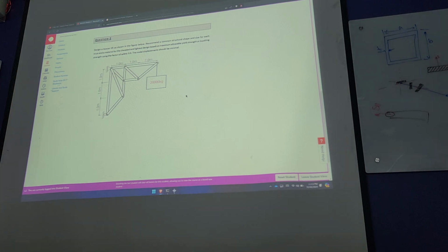One important thing, it's worth remembering: Abaqus does not keep units. So Abaqus, no units. Yeah, this one. No units. So it's you who needs to make sure that you're using the right units.